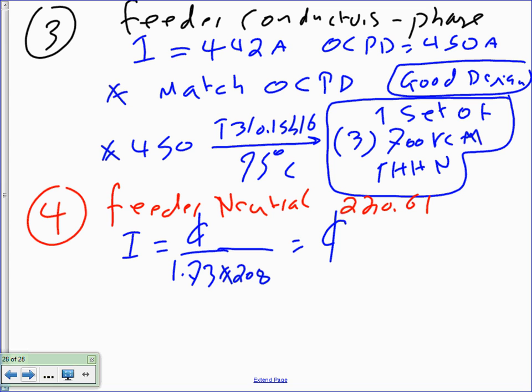Now, that's where you're going to use a kind of judgment where we don't have to have a neutral. What would you pull one for future? More than likely. Now again, that's judgment. Judgment based on what we have. If this is exactly what we have on our load, I wouldn't put a neutral. Now, if I don't know and I want one for the future, like you said, then I would probably pull one. So one solution is no neutral conductor. That's solution 1. I don't need a neutral.